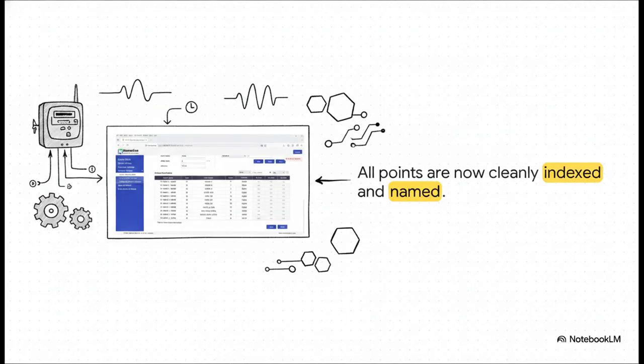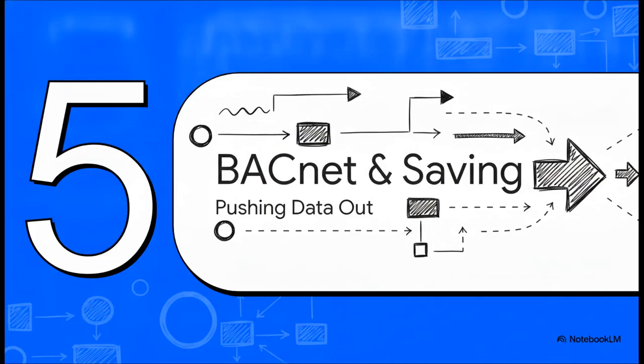After repeating this offset process for all the specific variables listed in your datasheet, current B, current C, voltage AB, active power, and of course that frequency point from our second group, you get rewarded with this beautifully organized Modbus point details list. As you can see, every vital metric from the energy meter is now cleanly indexed and perfectly named.